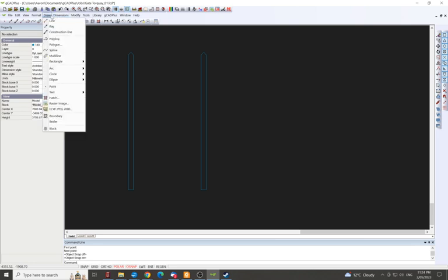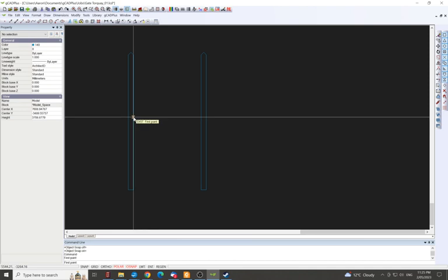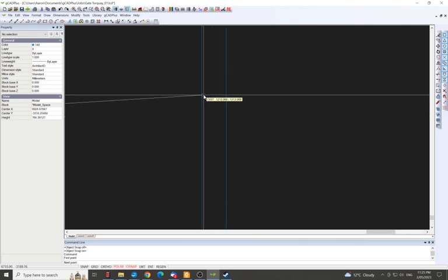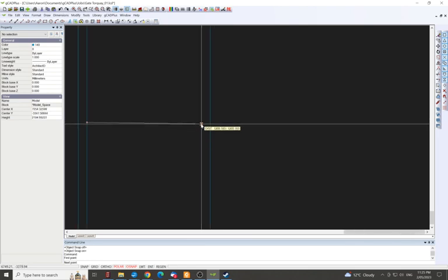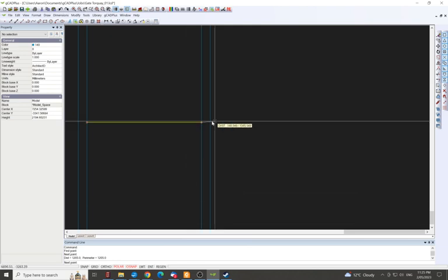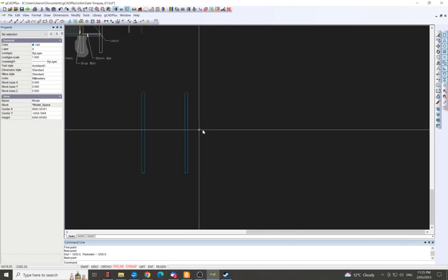Let's go back to tools. So distance. See, distance snaps on at 0. It's polar tracking, but then once it gets onto that, there's no more polar tracking left. It just slides along the actual whatever it's snapped to. So you can try and get it as straight as you can. Let's see. Go to there, but even there's 1205.0, so that's perfect. So just with the guide of the crosshairs, we got that right. So 1205 is what we want.